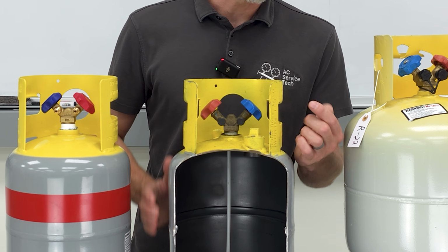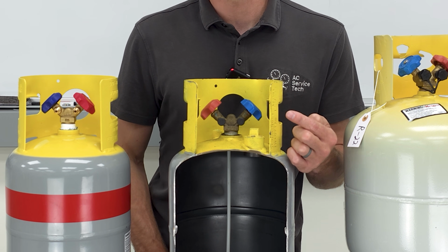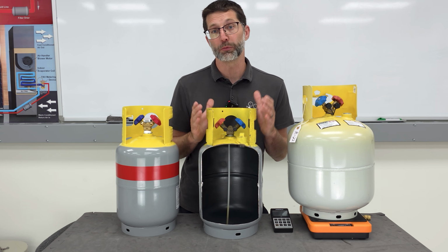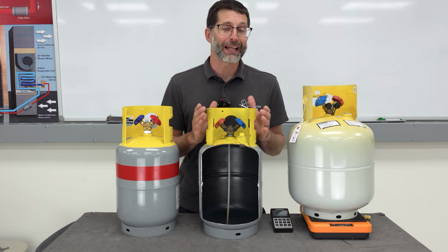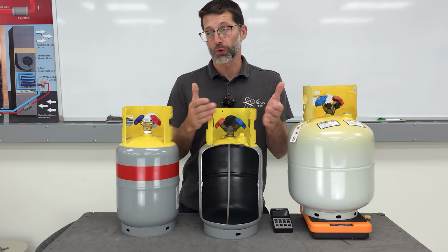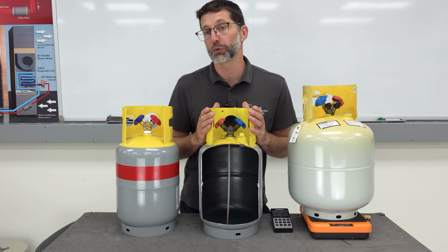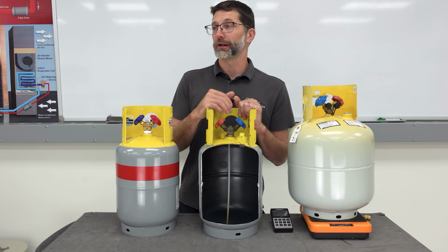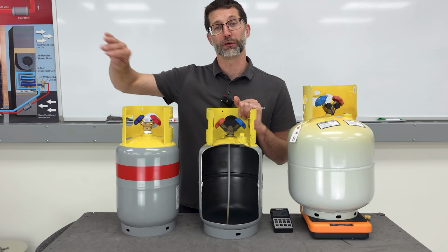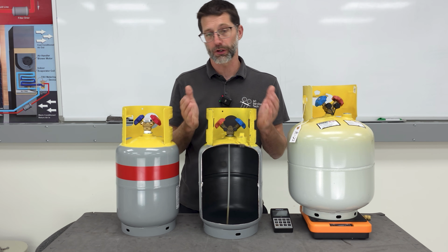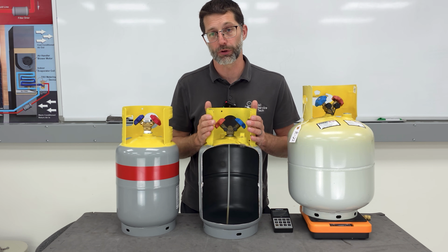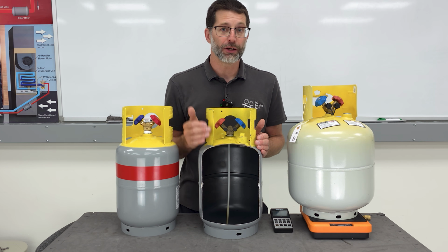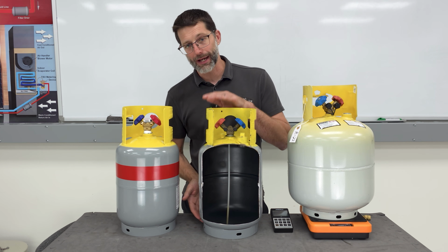And so then you need to look at the neck of the bottle and see your water capacity and tare weight. So you'll take the water capacity times 0.8, and then you take that times the specific gravity, and we're going to use a specific gravity at 120 degrees for R-410A. So say it's hot outside, and the refrigerant exiting the recovery machine is high in temperature. So we're going to use that figure for our R-410A refrigerant. So you take that, you add your tare weight, and that's going to give you the max weight.